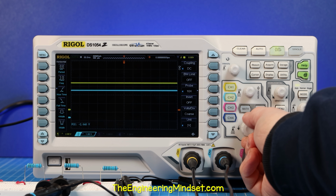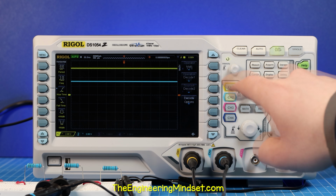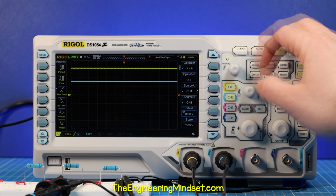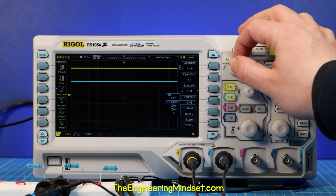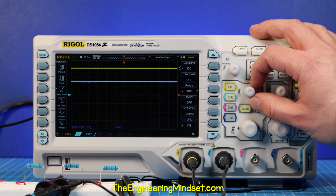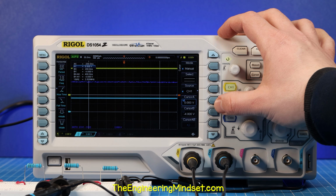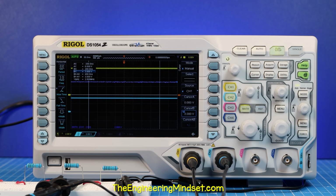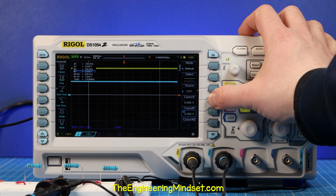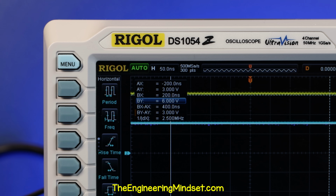Ensure both channels are on the same scale and that they are aligned. We could press the math button and select A-B, then select the correct channels, turn the operation on, and it will display the difference on screen as a signal. In this example, it's hidden behind channel 2, so I'll move that. We can then use the horizontal cursor lines to measure this. Then align the cursor lines with the channel signal lines, and the BY/AY value tells us the voltage drop.